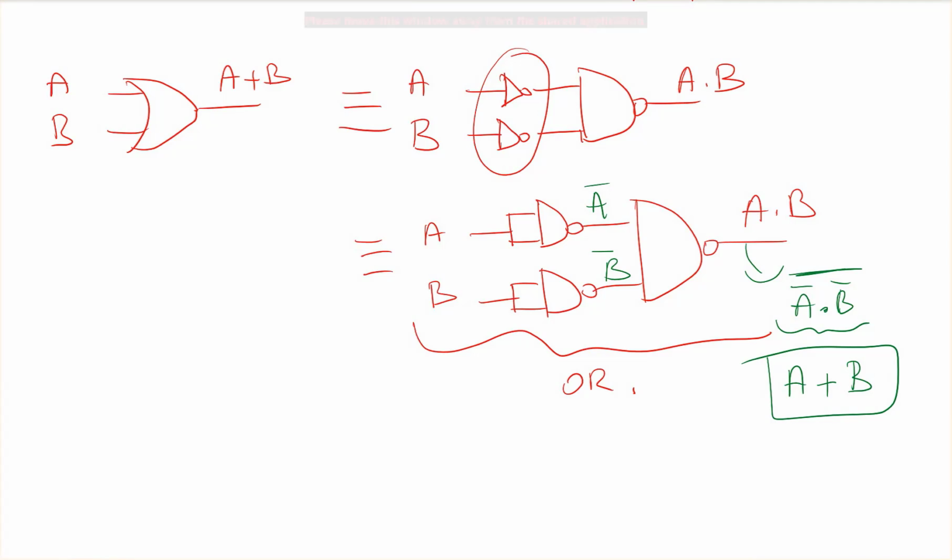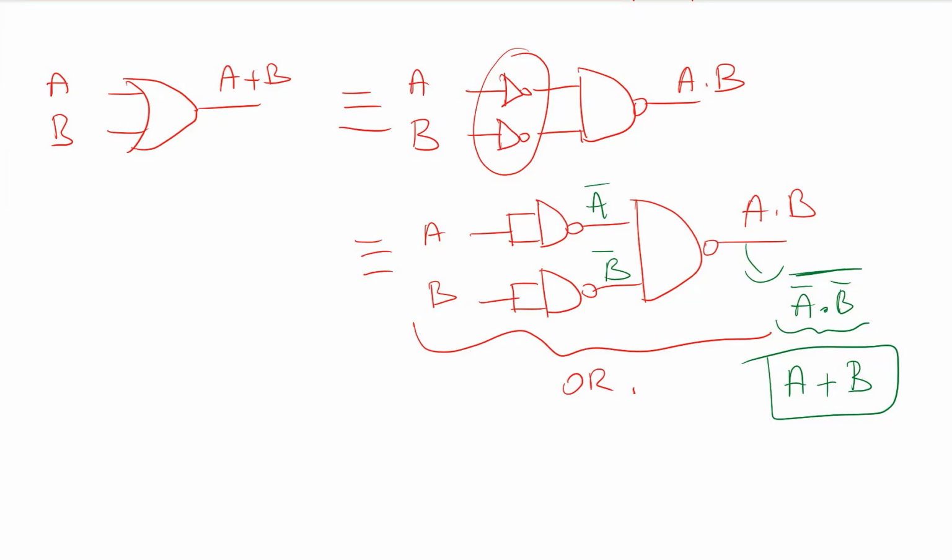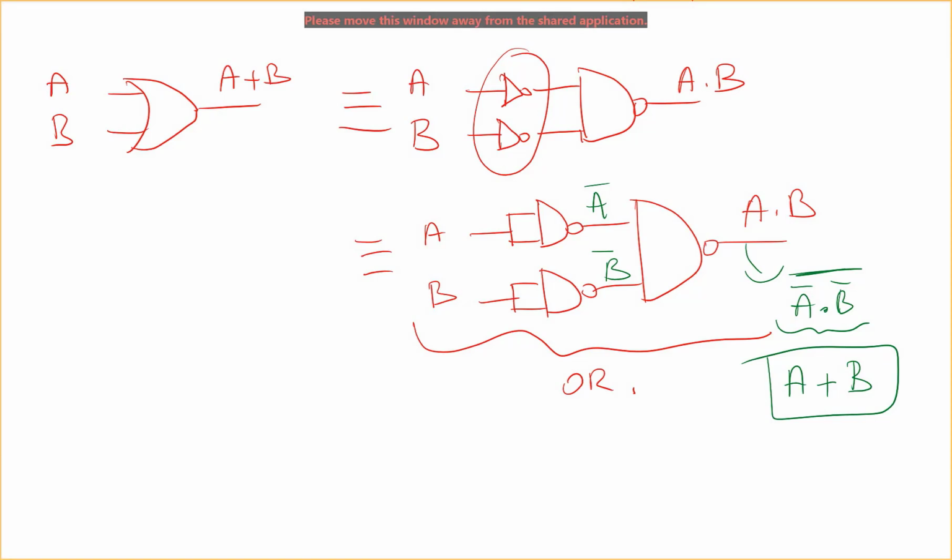So why do we do this? Why do we try to implement everything with a NAND gate? Basically, in some cases, you may not have any other gate. In some designs, all you have may be some NAND gates, and you need to do some additional operation in your design, and then using only NAND gates, you can implement any function. So it might be useful in some cases. Also, it is good to see how we can transform our functions from one way to another.